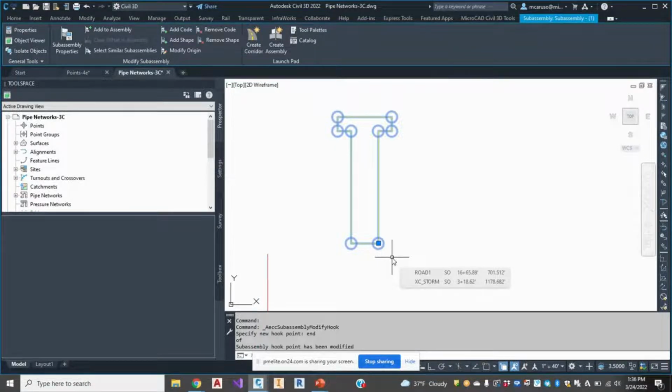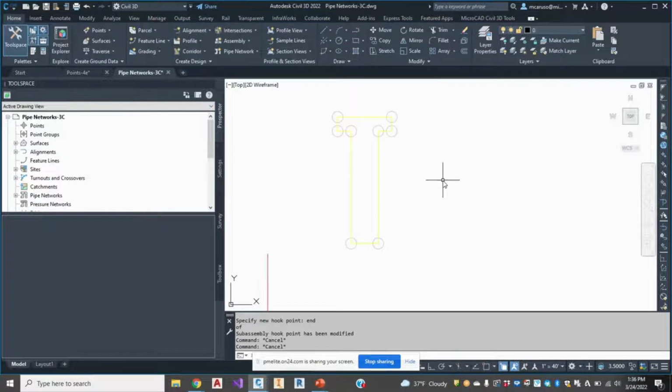Now there's an advanced tool that comes with Civil 3D called Subassembly Composer. It's a separate program, and that will let you kind of do the same thing, but you can assign actions and parameters, and they can stretch when needed, and it gets a little more advanced. But for a nice little static shape like this, this command will work perfectly.